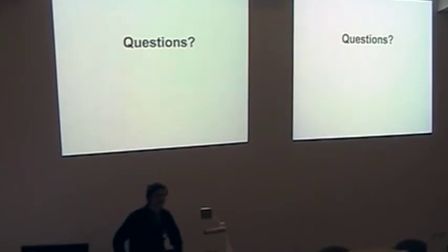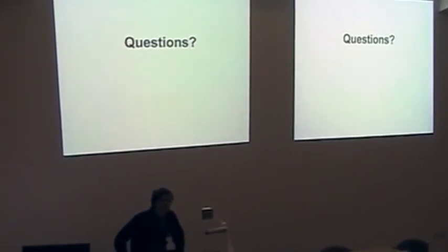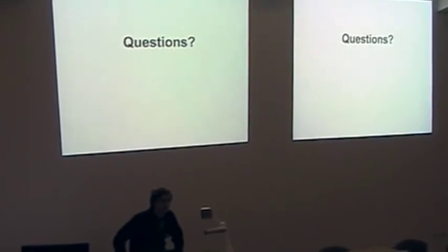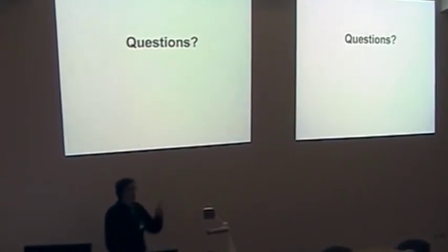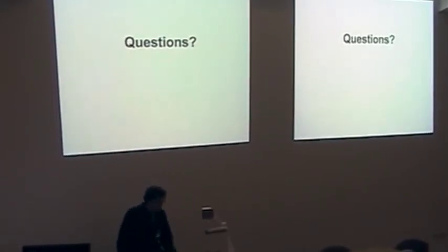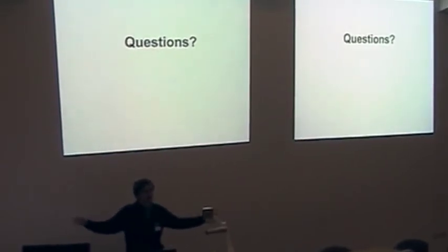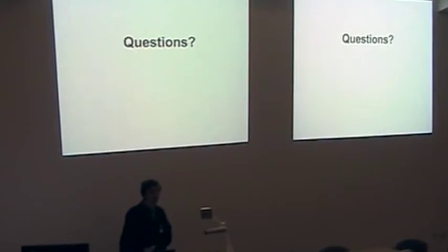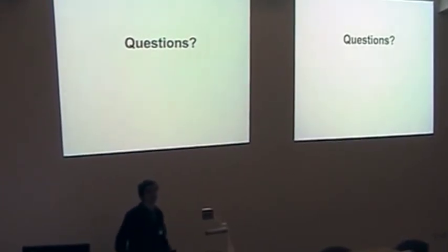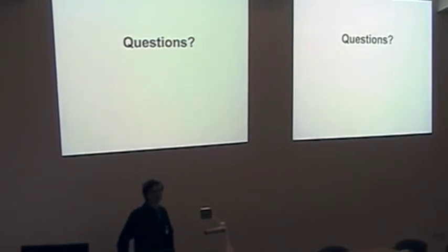One more question actually. Since this is a module and it's all abstracted, why aren't we talking to the Bus Pirate in text mode? Because I really don't like doing silly parsing. Also, a lot of the I/O is intended for humans to read, so it prints out a long string of text, and that takes a long time to send over the serial line. Whereas the binary I/O mode is just single bytes here and there. It's just faster.